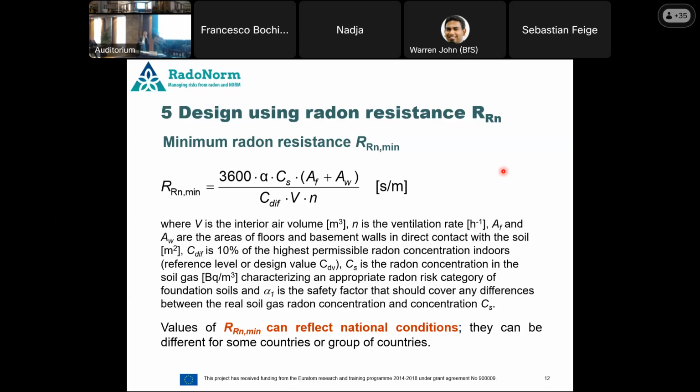But again, it probably depends on the building habits in each country, because in Central Europe, where we have clay soils, which are not so permeable, where we have high underground water table levels, it's quite common to use waterproof products. So the contractors know how to fix it and how to apply the waterproofing materials.